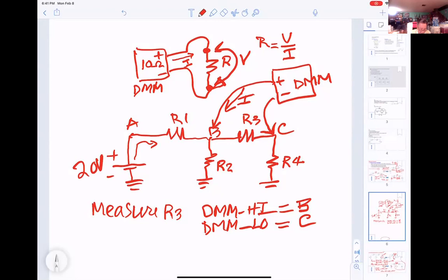So now they say, take that out. Okay. But when you take it out here, you still cannot measure to get the right value. You understand why? Yeah, because R3 and R4 are in series, but they're in parallel with R2 because R2 and R4 are grounded. Okay, so now I can tell you when the current I goes this way, current I here.